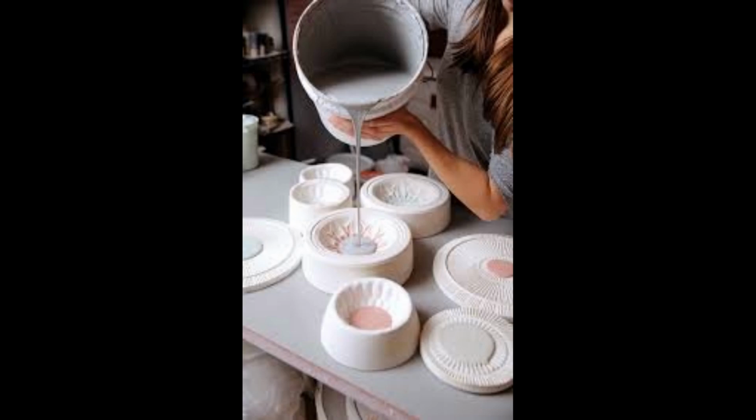If you don't know what slip casting is, there's a ton of resources online you can check out, but all I'll say is, unless you are making something out of ceramic, you would basically never do this. You also have to be aware that unlike urethane and silicone liners, the plaster is not flexible, and so you cannot have undercuts or it'll stick in the mold. So that's the easy decision.